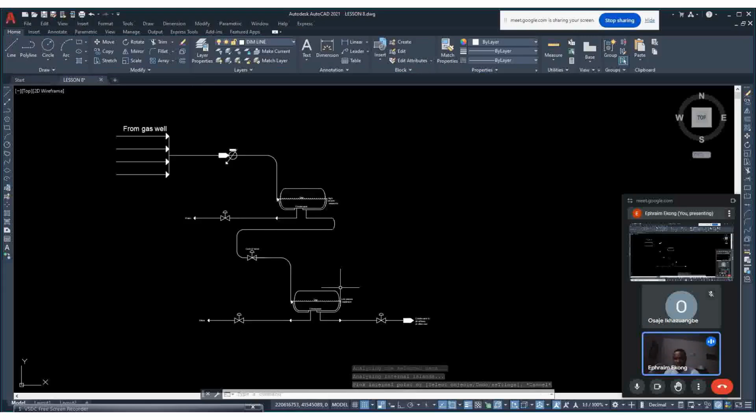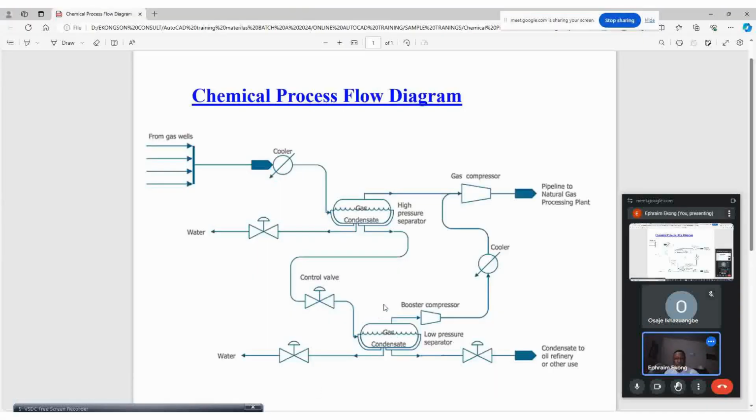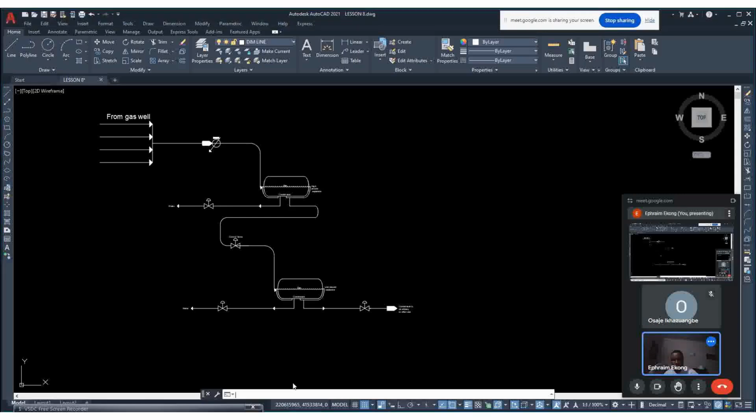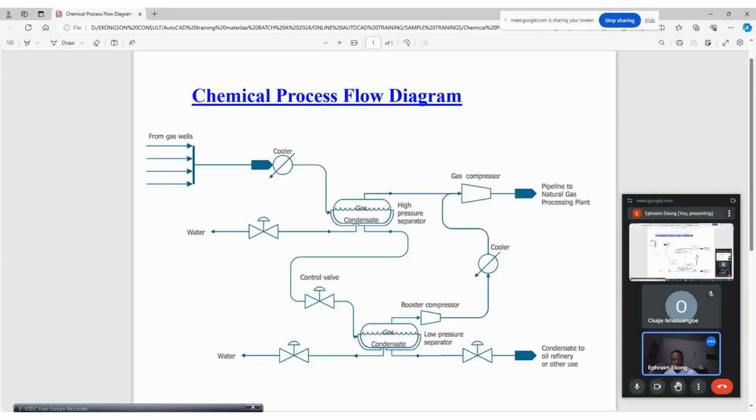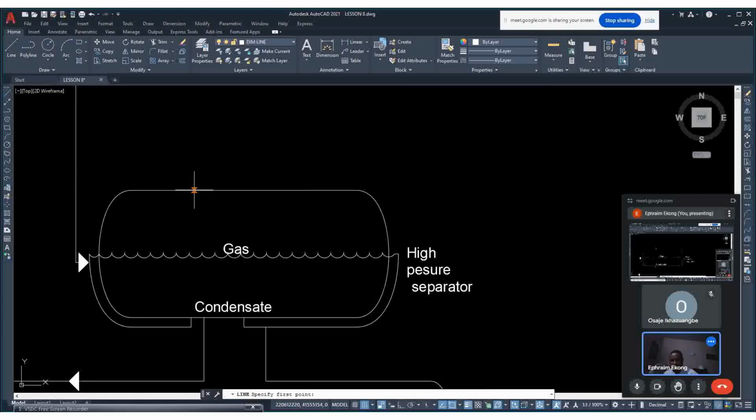Okay, so we are making progress. So what remains is this other part. Okay, so to do that, so we locate the midpoint. Click on line, then place your cursor along this line where it turns to triangle.